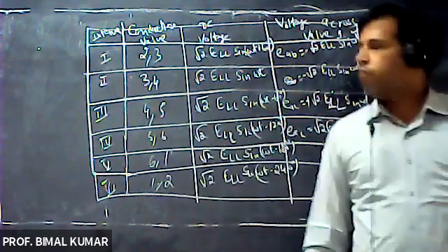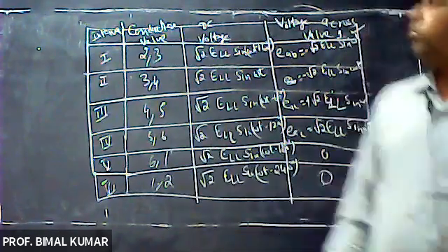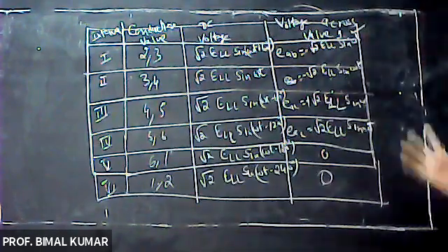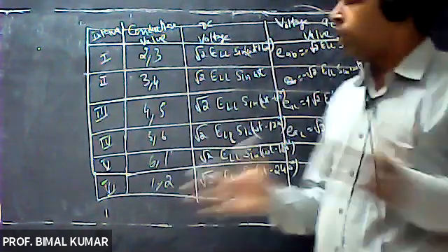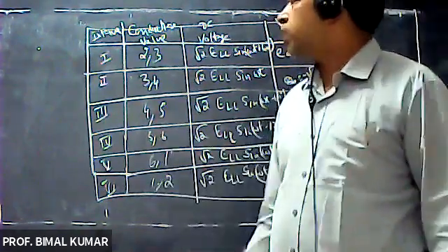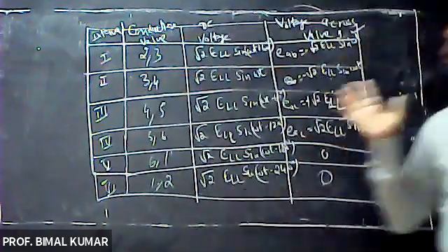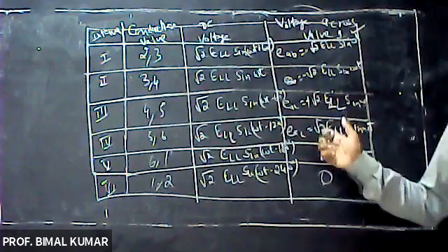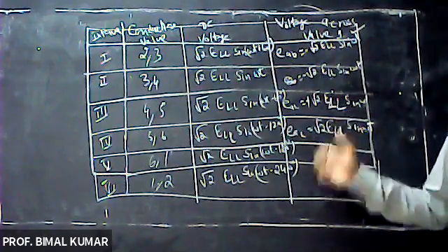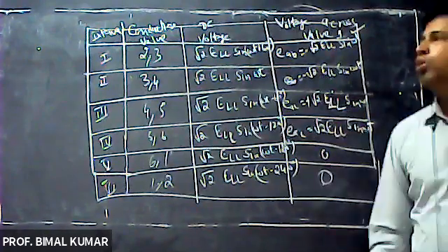That SCR1 or thyristor valve 1 will conduct. So whenever it conducts, the device acts as a short circuit. So the anode and cathode will be at the same potential. There will be no potential difference. So during that condition, the voltage across the valve will be 0.